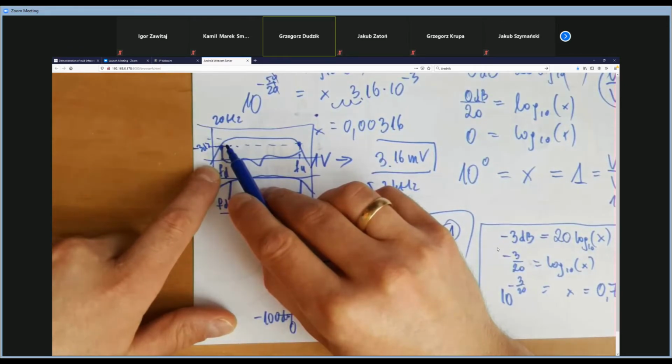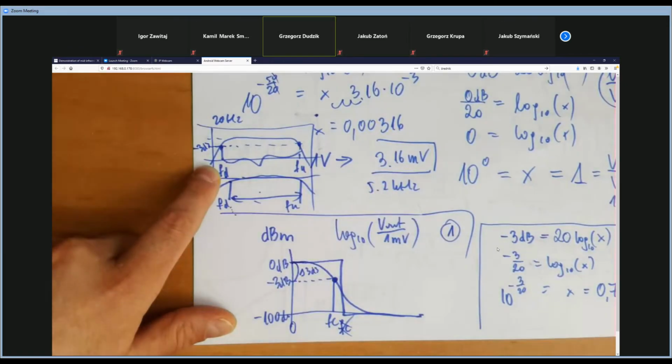So, for example, that's why if you plug your loudspeaker into the amplifier and you have very, very low frequencies in the signal, this is the basses, in fact, you will see that the bass on the loudspeaker is a little bit weak, especially for very, very low frequencies, for example 20 hertz.